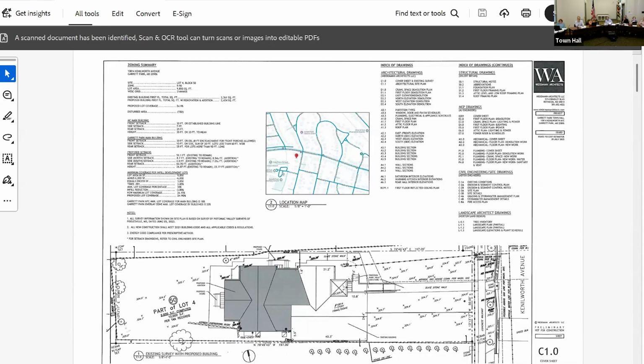So at this stage, we actually identify a manufacturer for the windows. I guess you all know that we presented to the Historic Preservation Commission, and they were enthusiastic about the project. One of the things they require is that replacement windows or windows that are being put in the historic portion need to be wood. All the ones in the back will be aluminum clad, for instance. So we specify all of that in the schedules so that the estimate can be based on those choices.